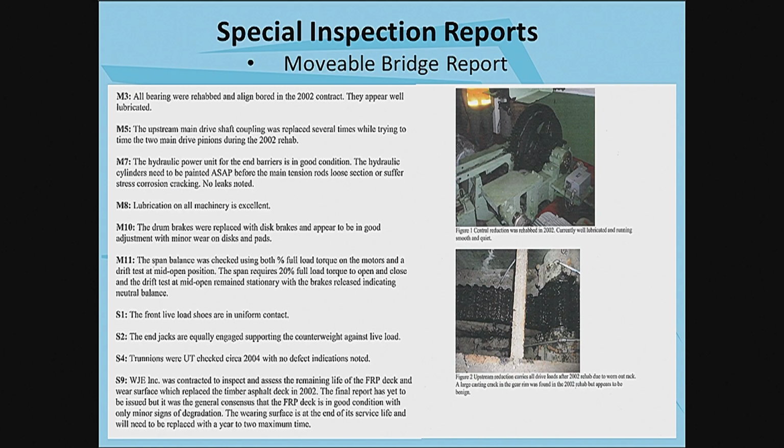The remarks and recommendations will be similar to any of the fatigue-prone, fracture critical. It will describe the condition of it, what needs to be fixed, how often that should be looked at, say greasing schedules, whether the electrical should be upgraded. We've done a lot of electrical work and mechanical work on our movable bridges. This isn't normally part of, if we're hiring a consultant or you may be doing your own inspections, generally you have to find an expert to do these movable bridge inspections. It's a specialized skill to do this.